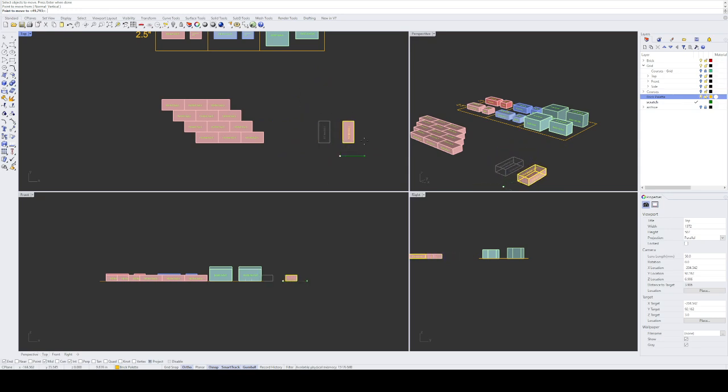That's a setting. And if you hit F8, it'll toggle that setting, right? So I hit F8, you can see it says ortho is off. So now I can move anywhere. If I hit F8 again, now ortho is back on. For your purposes, given that we're working with brick, you probably want to always have ortho on. So let's move, pick that thing, right? If I'm snapping, then it won't matter if ortho's on or not.